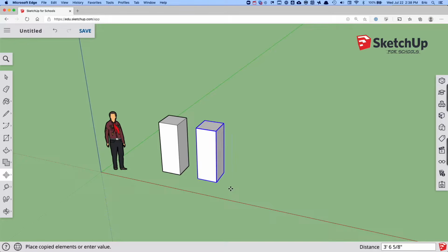Now, if I don't do anything else, I can just type in star, that means multiply, and you'll see the star appears in that distance box. And in this case, I'm going to type in 5. I'm going to press enter. Note that I didn't move my mouse over to that box and click in it. You can just start typing and it will automatically put this in there. So again, I typed *5 and I'm going to press enter or return.